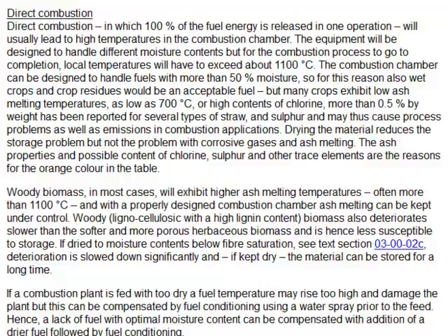The different designs will be apparent in the construction of the walls of the combustion chamber. And a combustion chamber designed to handle a dry fuel will not easily be able to handle a wet fuel or even a moist fuel. So the combustion chamber can be designed for wet, moist or dry fuels, and this holds true for woody fuels as well as for herbaceous fuels.